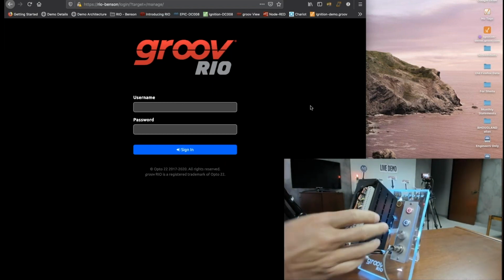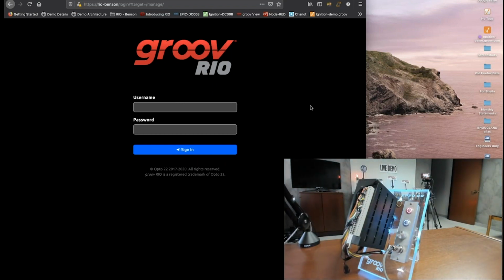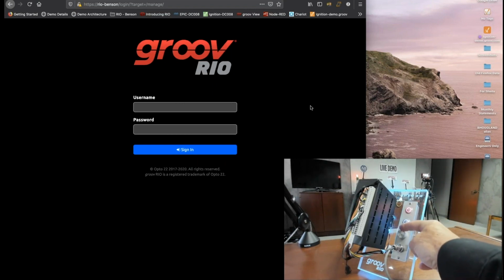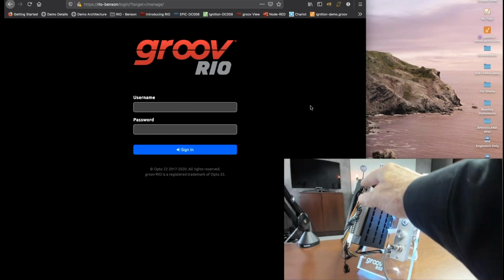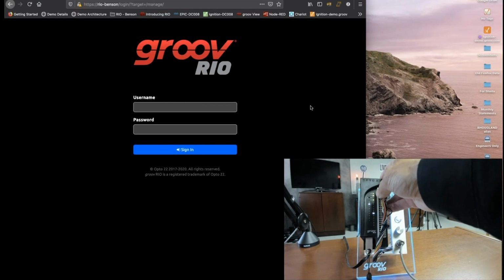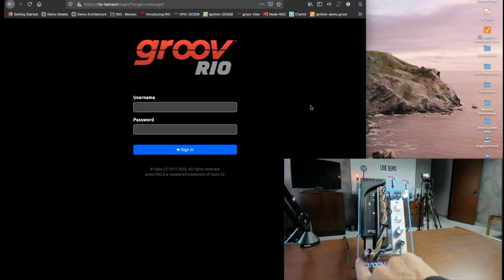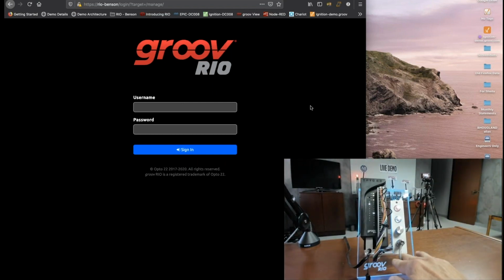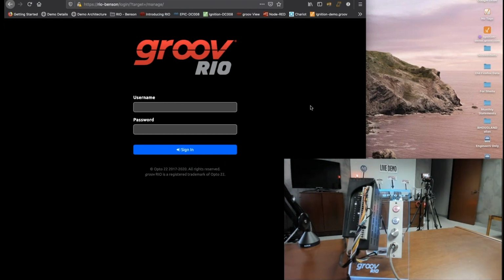I've also got a couple other things in here that I'm sure Jeff from Canary Labs and Arlen will be messing with from afar. One's a little blue LED here on this button. And then I'm going to show you a little bit more about this potentiometer, which is simulating a tank level. So by turning this, I'll be publishing the data that's wired right up here to this terminal, and publish that into infrastructure. Now note one other thing, that my PoE cable here is the only power to this device, so it indeed is powering my Groov Rio and all of my I/O. So that's pretty cool. All right, let's take a look at how this is done.